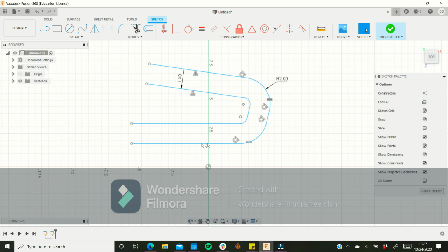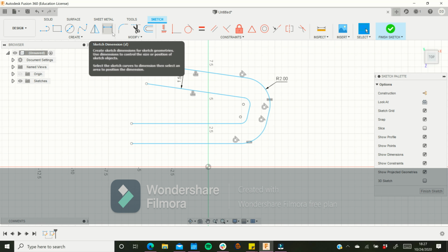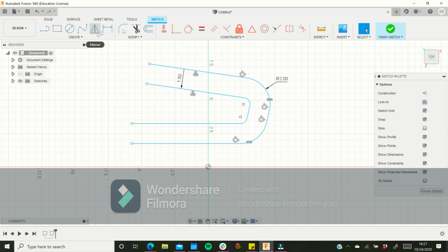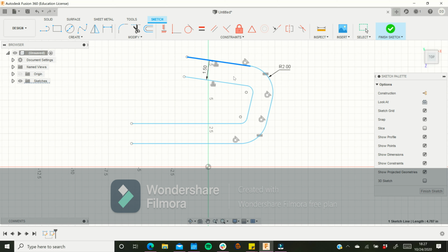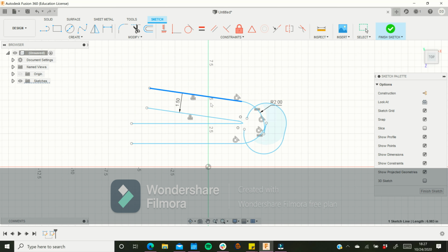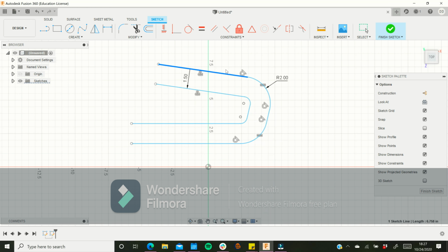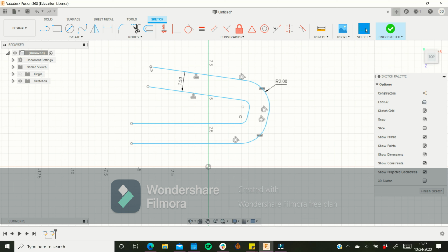So now I'll start showing you guys all the different constraints. Constraints are very important because without constraints and dimensions, I'll show you guys dimensions while I'm showing you guys constraints. Showing you guys constraints and dimensions is very important because it's how you define your part and how you make it a clean, good drawing. Like you don't want a blue design or drawing that you have, because then anybody could accidentally just drag it and change a bunch of stuff, and it's all just up to whatever's going on at that point. Like when you want things constrained, you want things dimensioned, you want things in place.